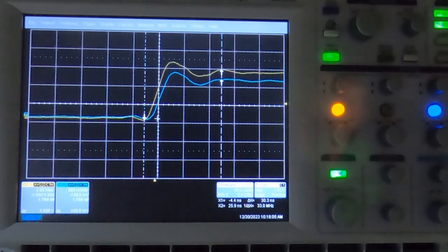But looking at a digital circuit on a vintage piece of equipment, that couple of nanoseconds is not really going to make any difference. So it is valid to use the lower cost probes. You don't need the expensive ones, and the same is true of the lower cost scope, although you do need a scope with at least a decent bandwidth to show squared up edges on the signals.